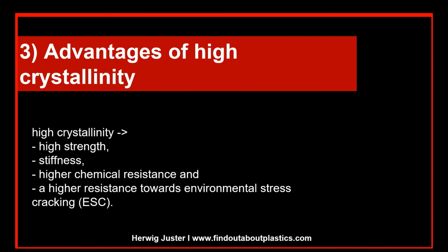Okay, so what are now the advantages of high crystallinity? So on the one hand, we already discussed the better the crystals form, the faster I have a modulus and can start the demolding. And high crystallinity also results in high strength, stiffness, higher chemical resistance, and higher resistance towards environmental stress cracking. So ESC, we'll also make a video on ESC later.